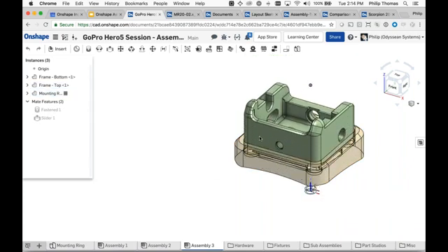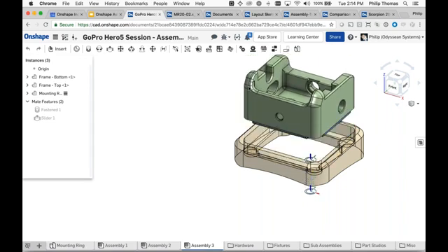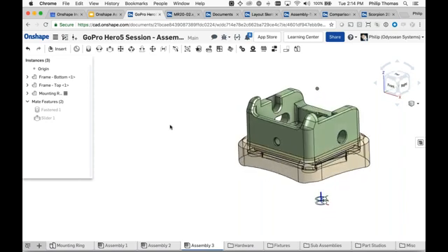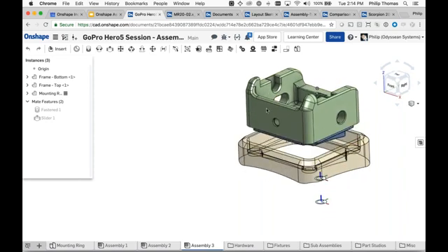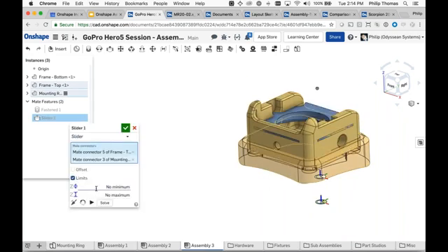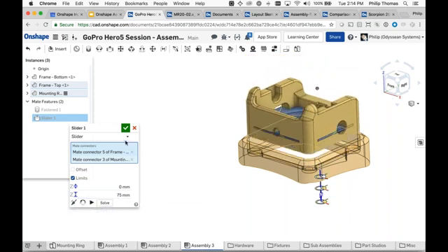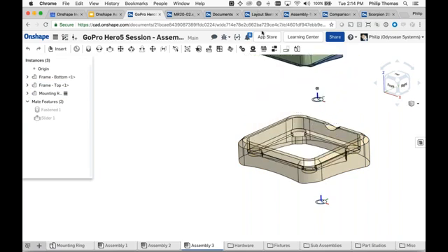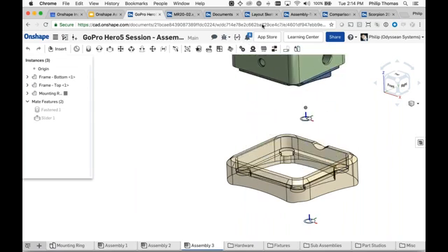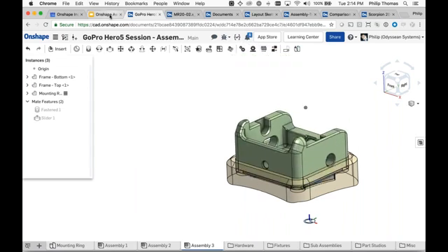Now you can see how it's very easy to mate together 3 parts that have no common obvious piece of geometry or location common to all 3. It's simple. You just make them common. What's nice also is that I can put limits on the slider very easily. The minimum is 0. Maximum always has to be bigger. So I'll say this is 75 millimeters, and I can have it animate between the fully open and fully closed. Now you can see, can't go any higher than that, can't go any lower than that. So I'm calling that the build 2. If you see him out there, tell him I said hi.